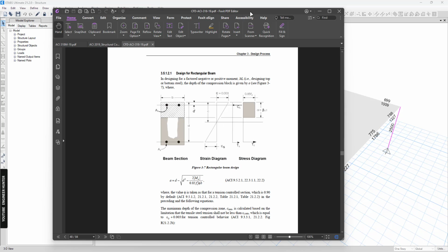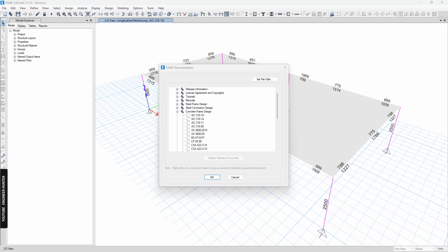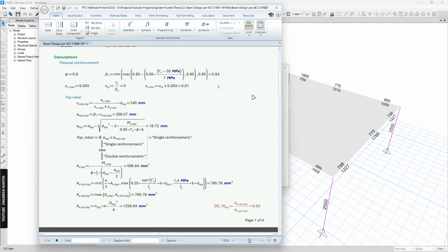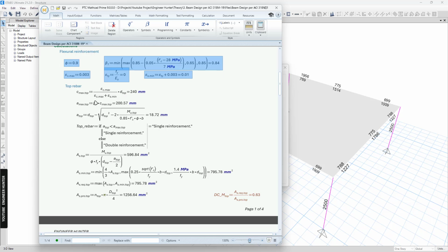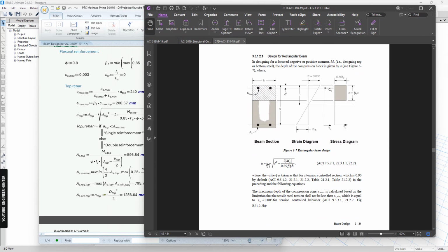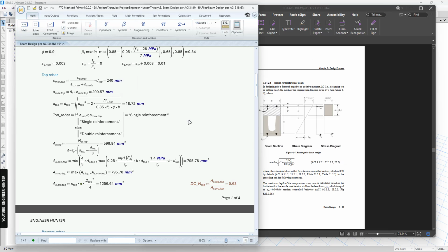Okay, so now we go back to our script. So once you know all this, you can compute for C, and I use the same formula here, so we can compute for A. So once we know the A here, we can compare with the A maximum, so we can know whether the rebar needs compression reinforcement or not.